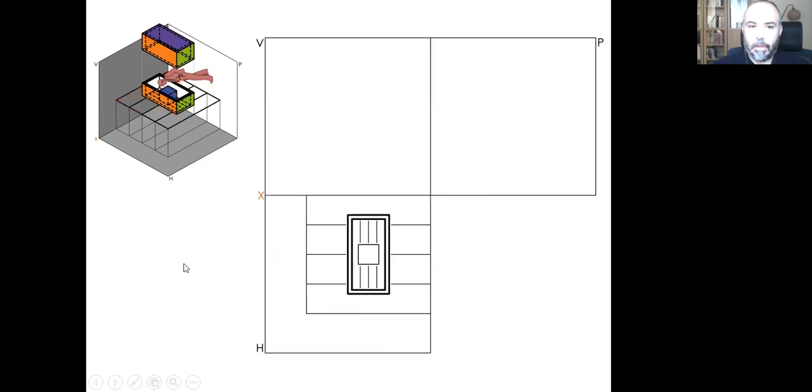And now it has been completed. I just need to check one more time. Are there any lines? Are there any objects that I left behind that I missed drawing, either cut or seen? No, I start drawing the cut surfaces here with the thickest and the darkest lines. And then I start the objects that I see. The closest one was the top of this cube here, and then the bottom of the rectangular prism, and last, the lowest object was this square horizontal plane with profile projecting lines over it.